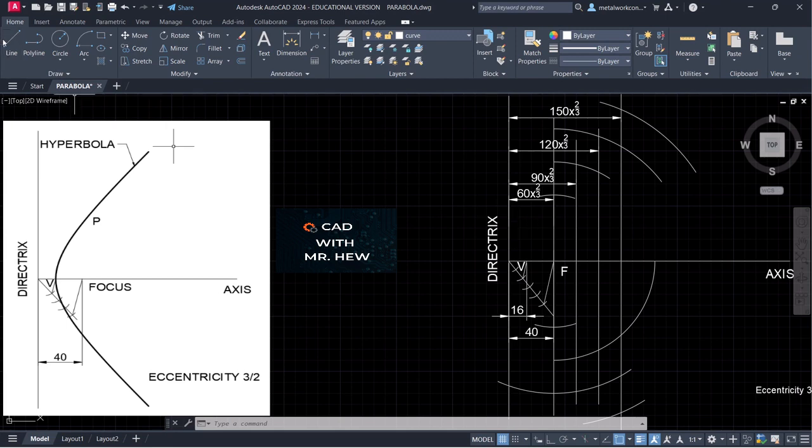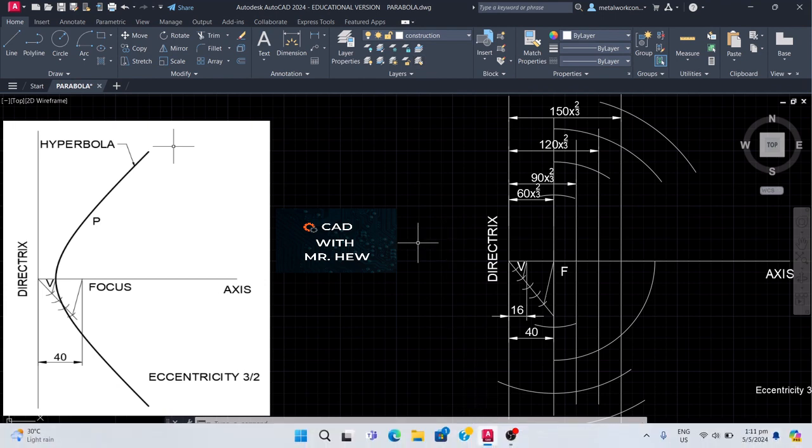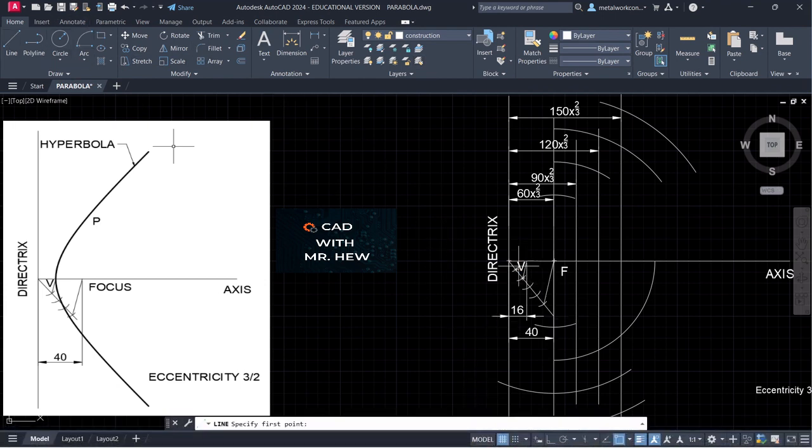So we're gonna go line in the construction layer. We're gonna go line. We're gonna come from here. We're gonna go over 26.66 this line. So what we can do, we can copy this line and put on it. All right. So we're gonna go copy the directrix, enter. I'm gonna move this point and I'm gonna put it at the end of the line that we drew there. If you turn off the snap,